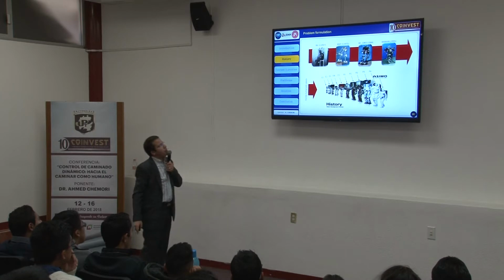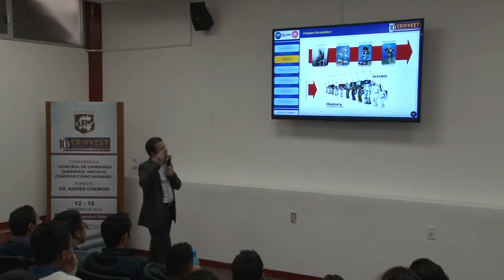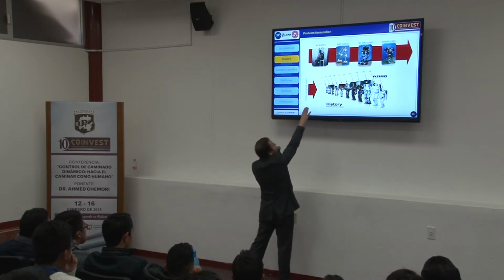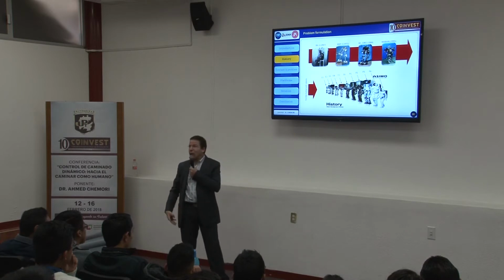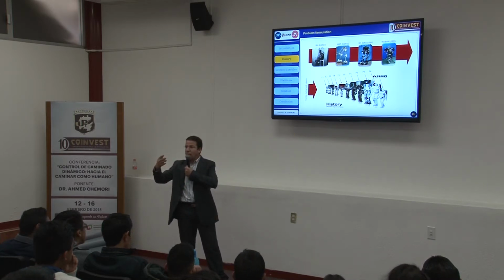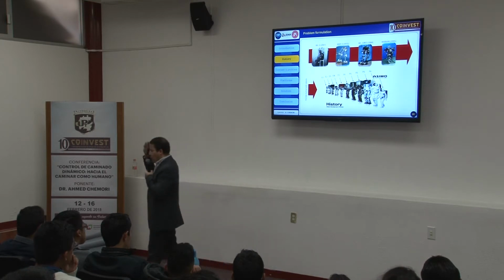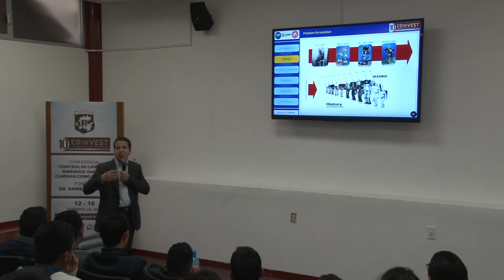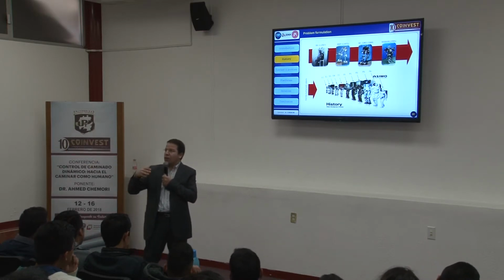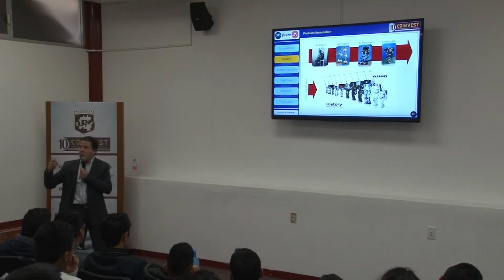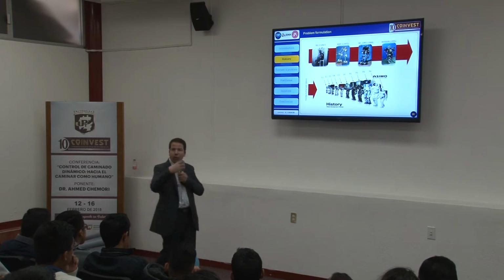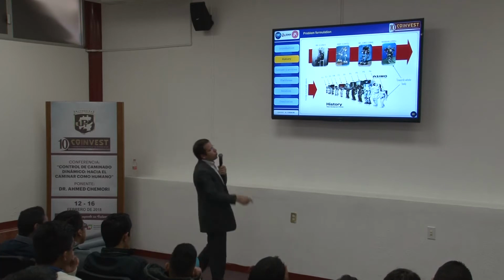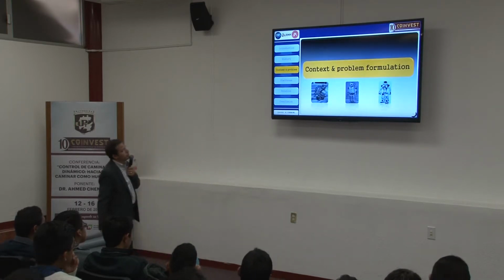And Waseda University also followed the same procedure, since if you look at the beginning, the first prototypes are only lower limbs. So there is no torso, no arms. Why? Because we think that, for instance, to reproduce human walking, you need just the two legs. You don't need the upper limbs. Yes, you can add the upper limbs. They can help with the stability of walking, to improve the performance and so on. But it's enough to reproduce this biped locomotion. This is why they start with just biped robots, and finally they go towards human whole body prototypes.